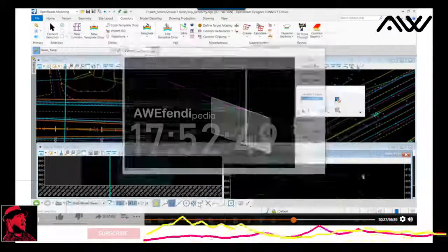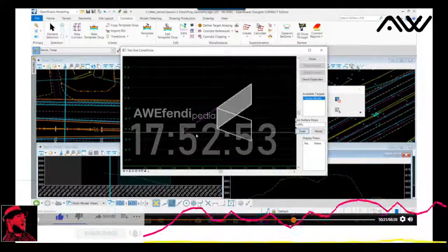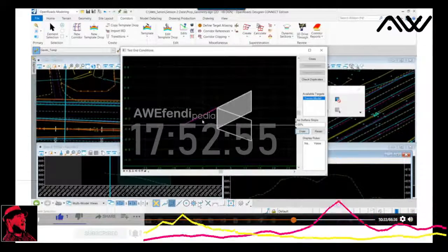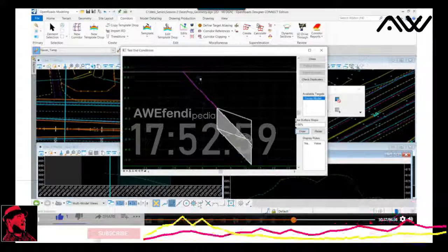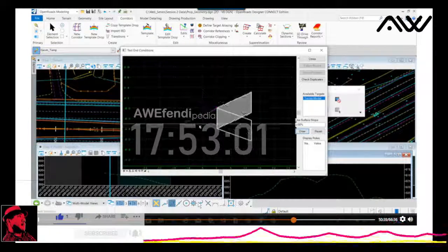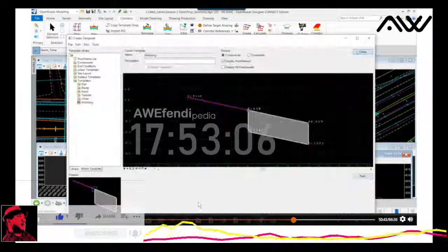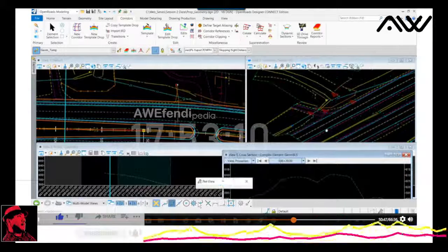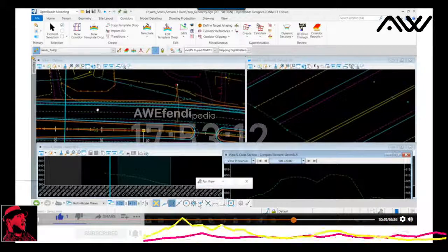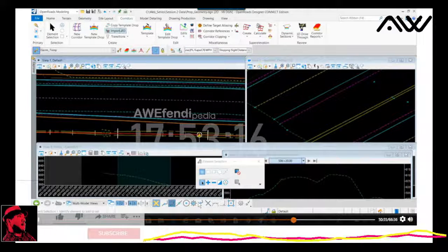It does nothing but follow the existing pavement. You'll notice how it's pivoting about the edge, and it follows the cross slope of the existing pavement and modifies the widened pavement to that existing cross slope. Now we're going to apply this template to the edge of pavement from the survey, and we're going to find that new PGL. Okay, so let's run that. We're going to apply that linear template.